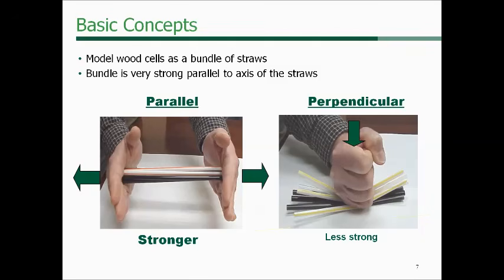If you were to look microscopically at inside of a 2x4, you'd see long strands along the length of that 2x4 parallel to grain that look something like straws. And so parallel to the axis of those straws, either in tension or compression parallel, wood is very strong. In the other direction, however, whether we're talking about compression perpendicular to grain or the opposite, which is tension perpendicular to grain, wood is less strong. In fact, tension perpendicular to grain is sort of the Achilles heel for wood members.